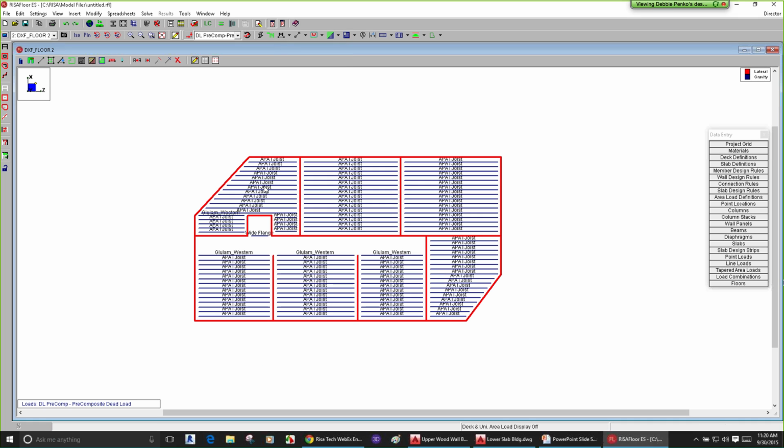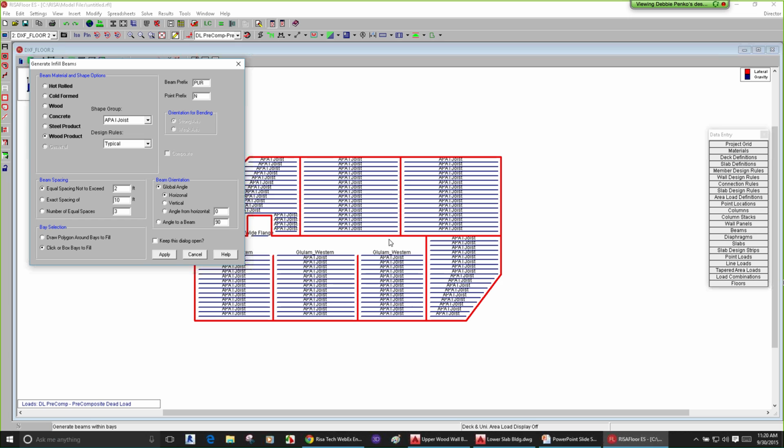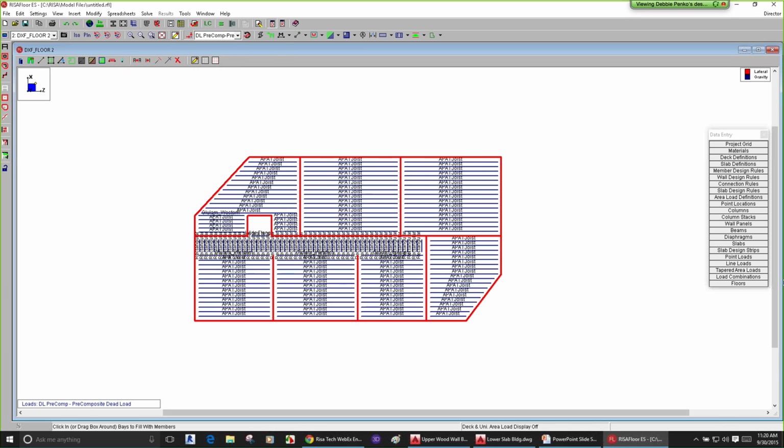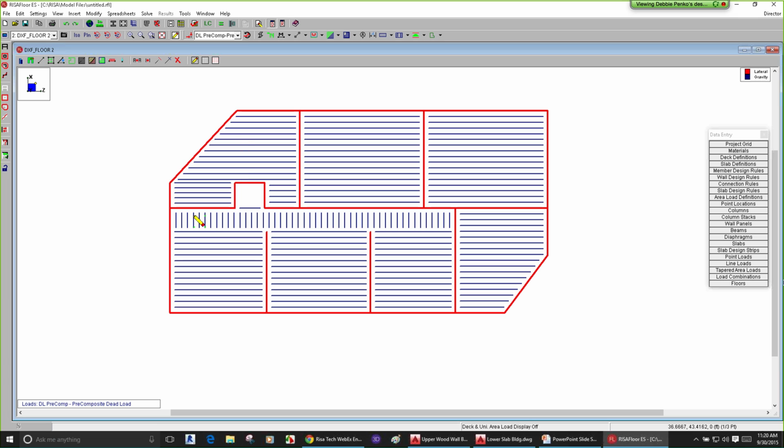So next thing to do here before we move past that, the hallway is pretty blank. I'm just going to put some wood beams in place there, vertical instead. So I'm just going to change the direction of the framing. So let's turn that off now that it got a little crowded in there. And we can see I have wood beams across my hallway area, and I have all of my framing going in the horizontal direction for my I-joist. So I've got all that in place.